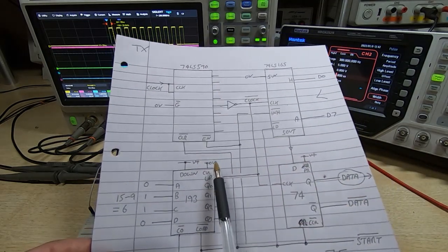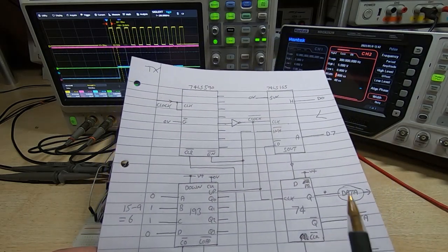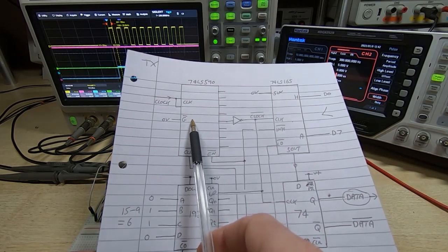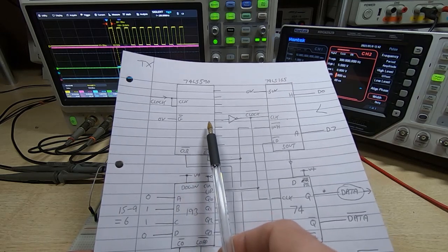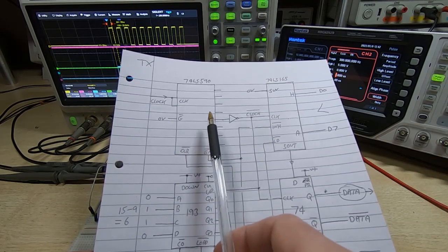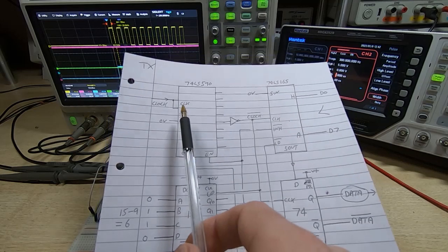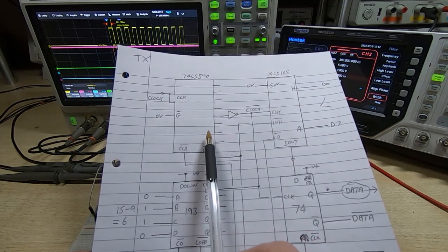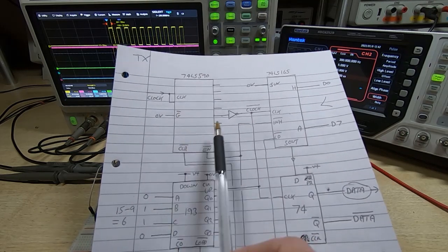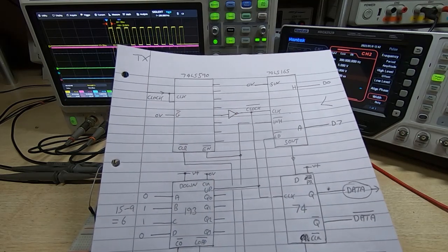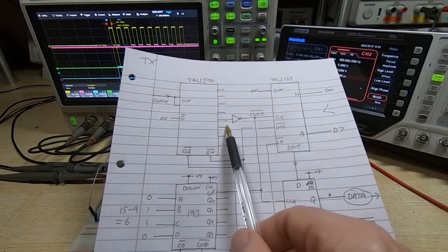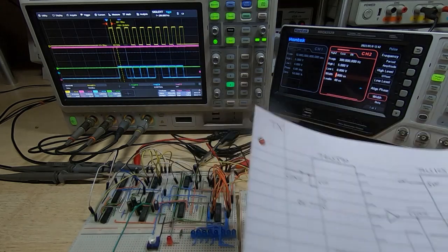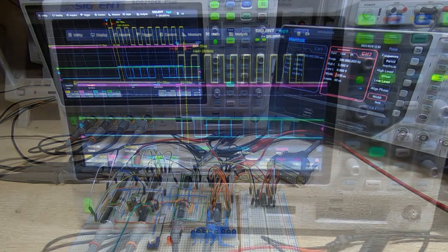So we reset this as part of the start process when we apply the start pulse to it, and that causes the internal counter to be cleared, but it does not clear the register. The register is only updated at the next clock pulse, which means that when the start pulse arrives, the counter is cleared to 0, but the output from the registers is not. And it does not get cleared until the next clock pulse arrives, and we'll have a look on the scope as to what effect that has.